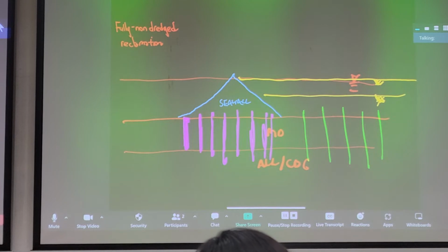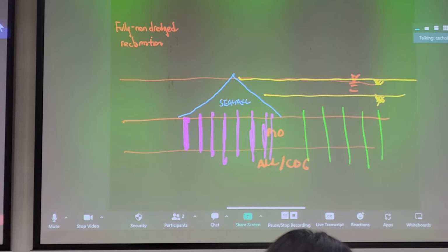Now, the problem being, you have to use deep replacement if you use stone columns, and there's additional costs accrued. There's also technical difficulties because not everyone is familiar with how to use stone columns. There's not too much experience. The stone columns serve a few functions. Stone columns also act as drains. In fact, they're much more pervious than band drains, PVD drains, because they're much larger diameter. It's just a rock, basically a column.